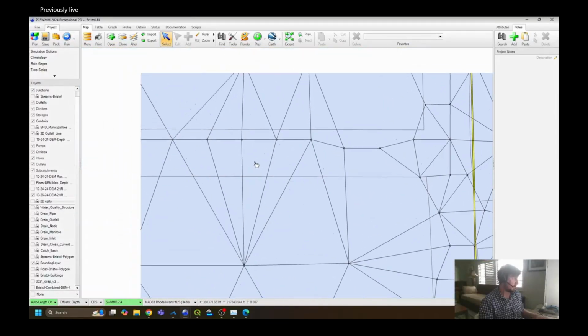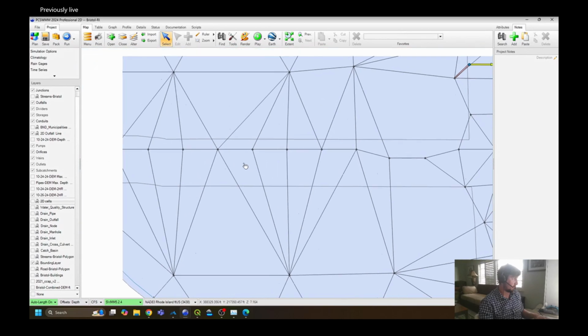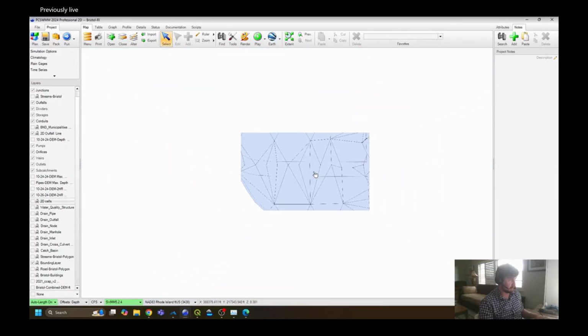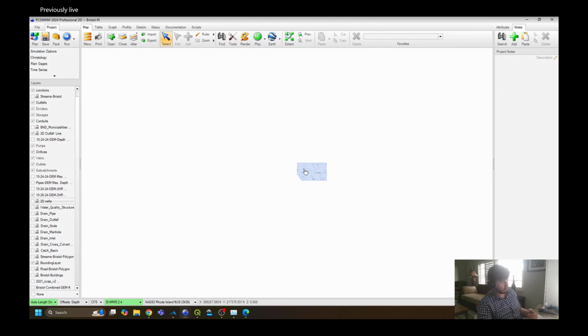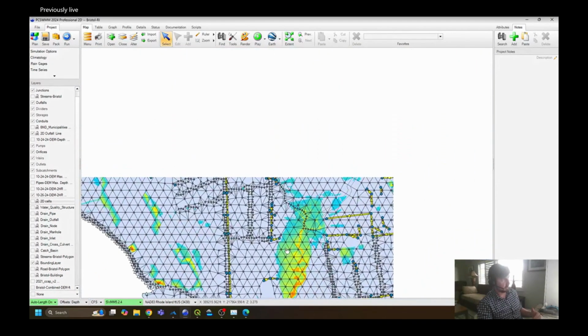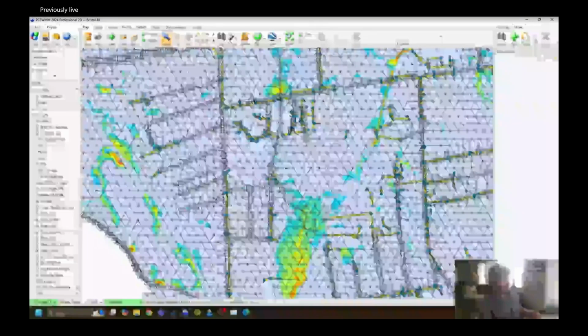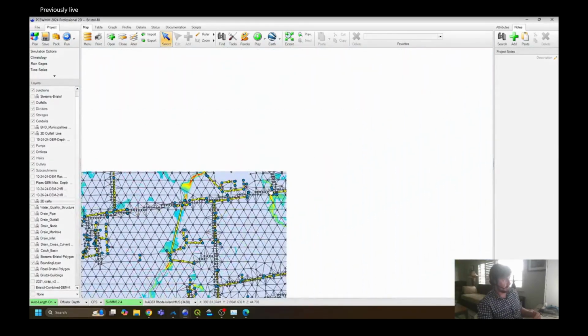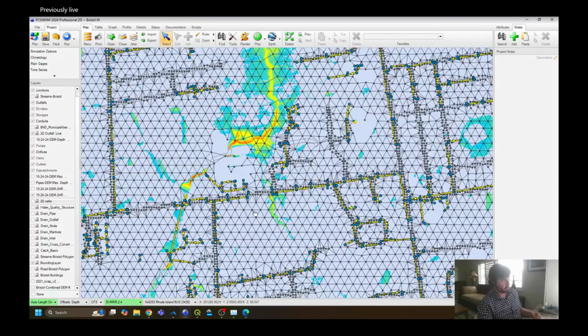If I go on this road, I should have made this high resolution. Maybe this is obvious, maybe it's not, but I took my polygon from my road and gave it a different type of condition, so that when I create my mesh, it knows without me having to draw every polygon to give my roads a higher resolution mesh. I want it to have a lower Manning's roughness when it builds my conduits. And then I want to give my regular surface a lower resolution.